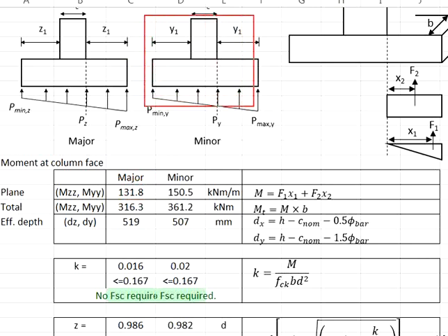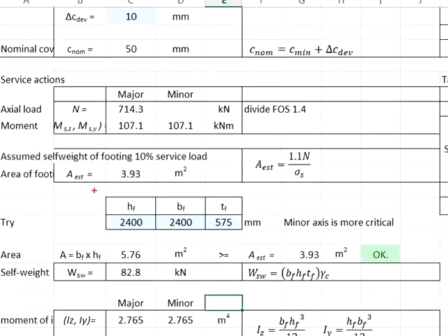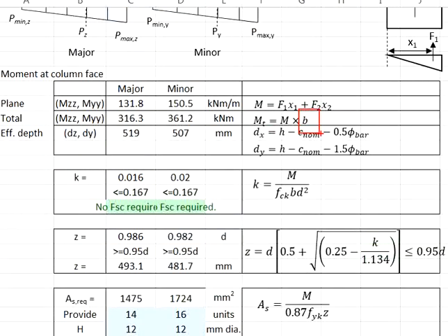As for the minor axis, this will be the width. Take the moment, multiply by the width here, you get this. Since the proposed pad footing is square in shape, the width B here for the major and the minor axis will be the same. That will be 2.4 meters. Later, you will use this to design for the moment resistance.